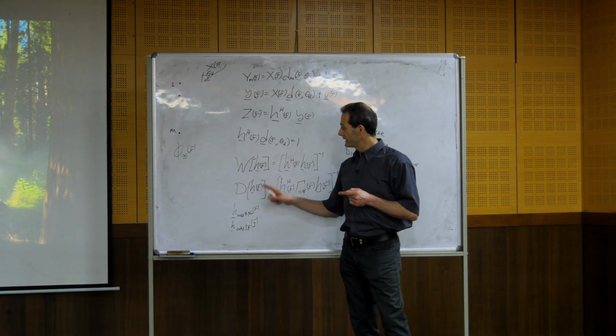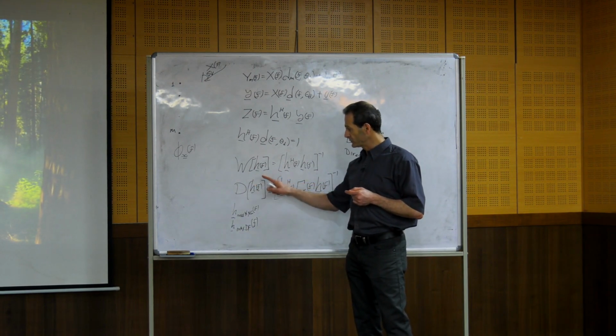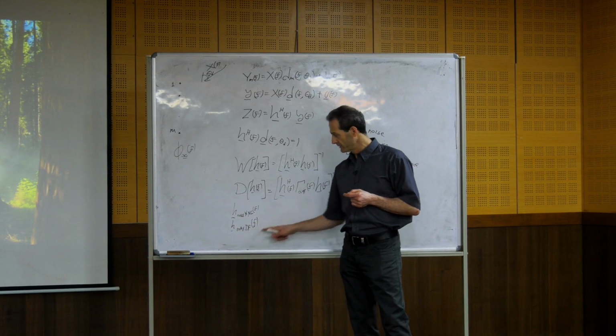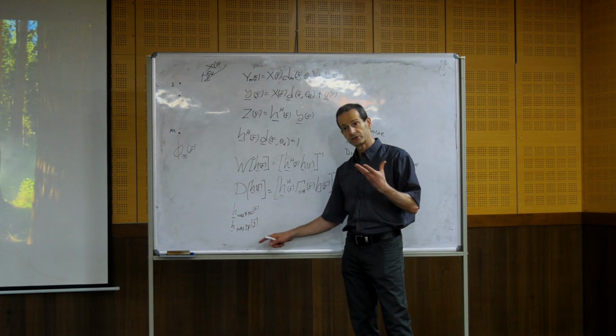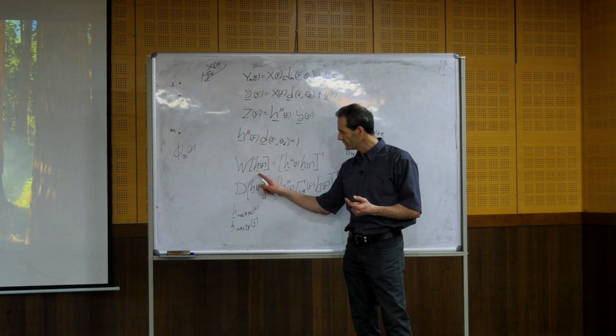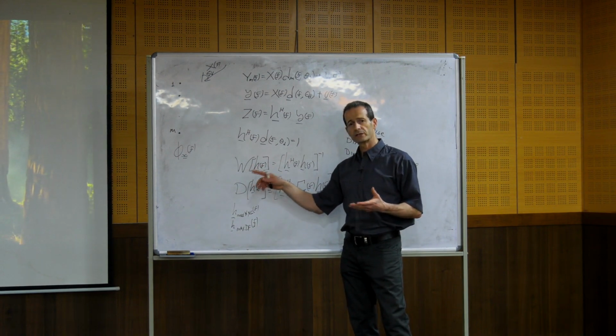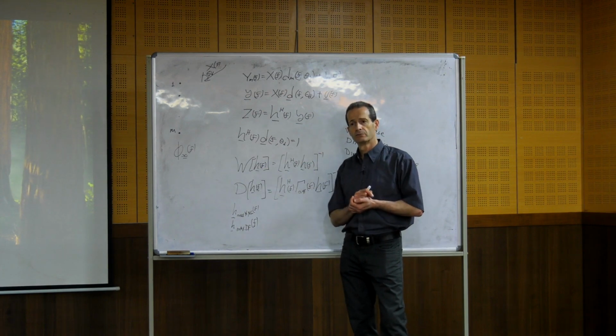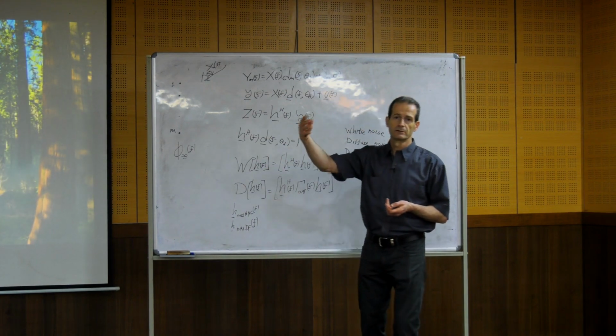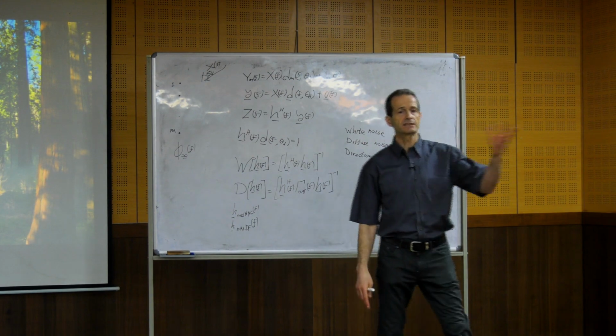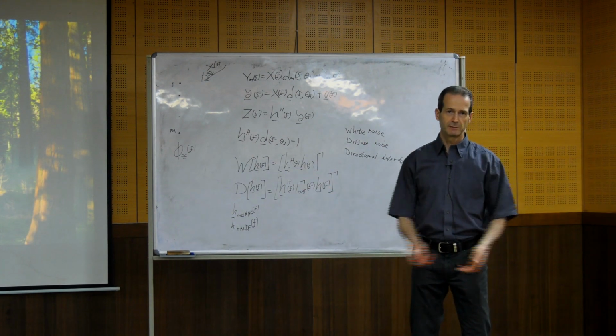Which means that the white noise gain that we will achieve using this beamformer, designed to maximize the directivity factor, will be very low. It can be minus 50 dB, minus 60 dB, minus 100 dB.